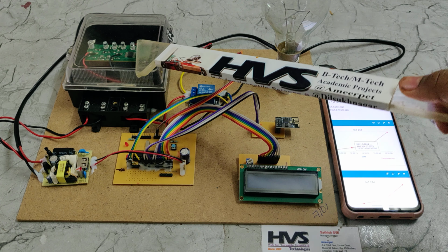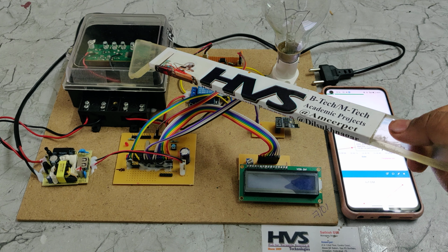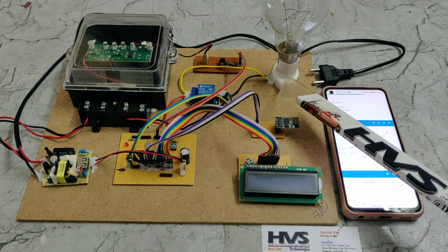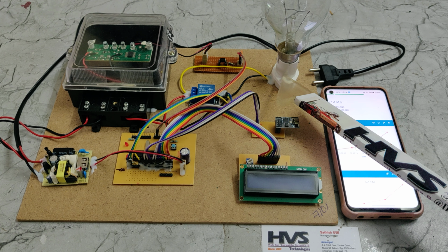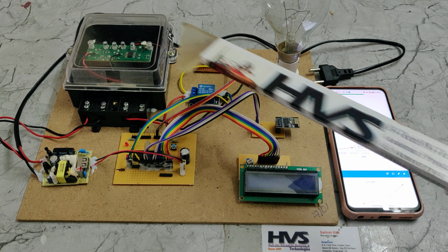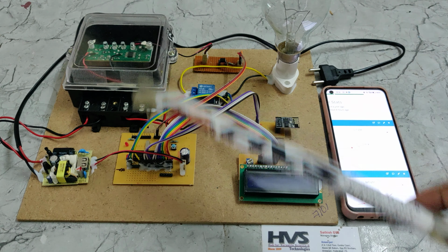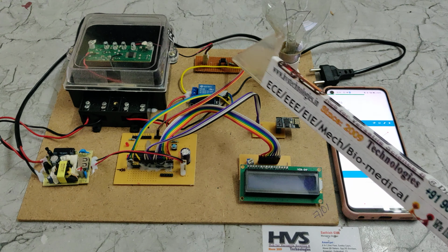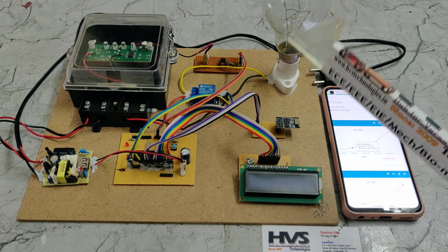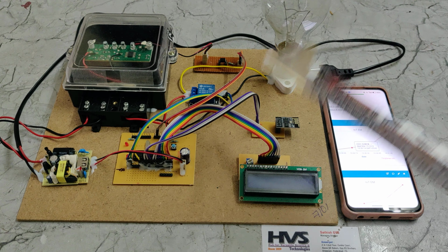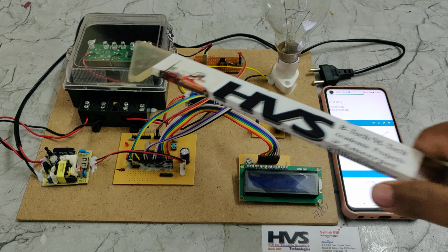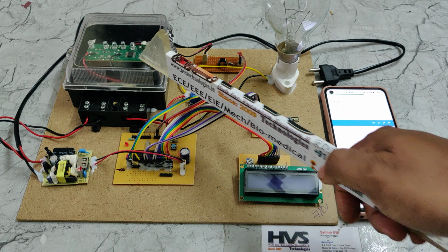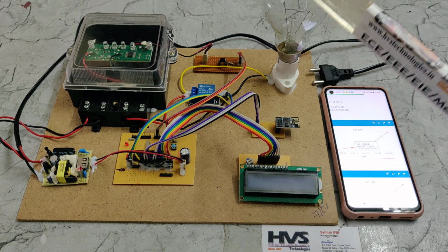Whenever the blink count reaches 3200, then the load connected has consumed one kWh, 1000 watts per hour, completed. Meaning if the light blink count keeps going up to 3200, that indicates the system consumed 1 kilowatt hour, meaning 1000 watts of power was consumed by this load. So if it's 1600, then 500 watts, like that. One blink is equal to 1 by 3200 kilowatt hour.